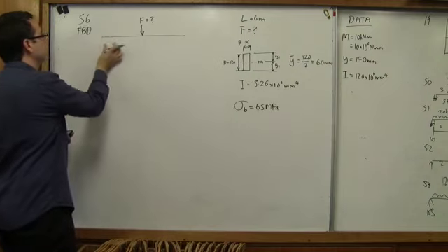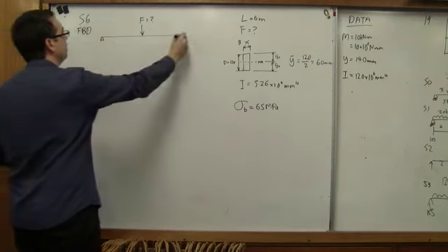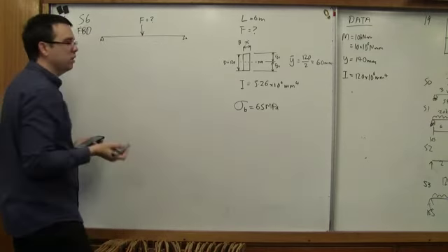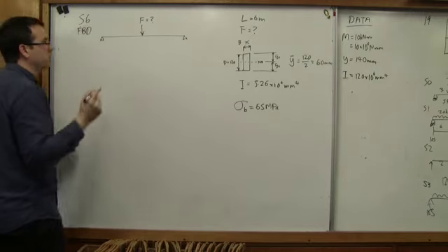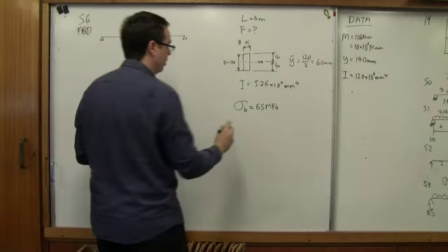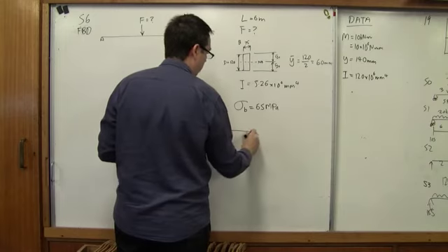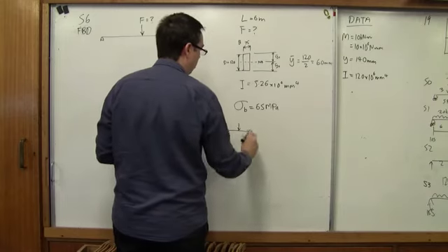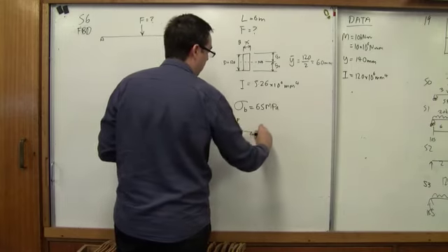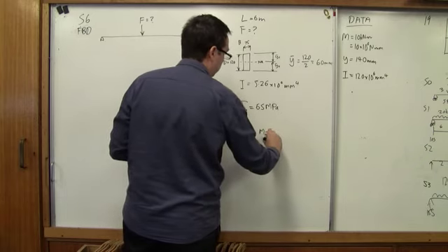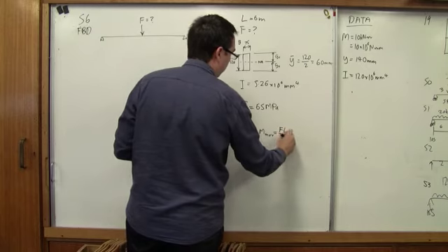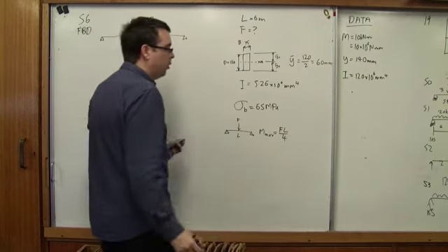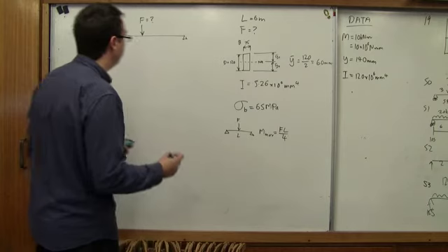They've told us that it's a simply supported beam, which means that we can't really draw a diagram, but we could. So first of all, I want to point out that we are allowed just to use this formula. We're allowed to say that for a simply supported beam that's symmetrical with a single load, M max equals FL on 4. We're allowed to do that. And we could rewrite that formula, but let's prove that first.